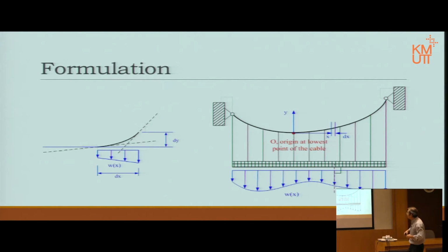So we know we can draw it. Now, because this is not a straight line, the tension will be at the points with different angles. In this case, we draw it along the tangent line. So that is the tangent line at the two points, and the two forces will look as such. Now on the left hand side, which is the starting point, usually x, and then we move this way by dx, right? So the starting point, let's say, has a tension that we call T. Now if we move along the cable by that small dx, we are not so sure it's going to be the same.